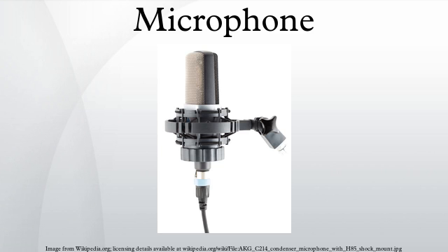Most microphones are designed not to have their impedance matched by the load they are connected to. Doing so can alter their frequency response and cause distortion, especially at high sound pressure levels. Certain ribbon and dynamic microphones are exceptions, due to the designer's assumption of a certain load impedance being part of the internal electroacoustical damping circuit of the microphone.